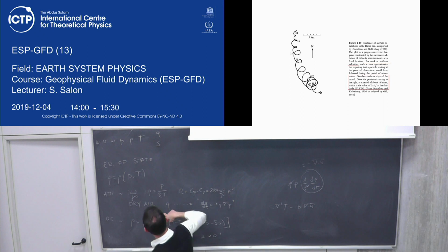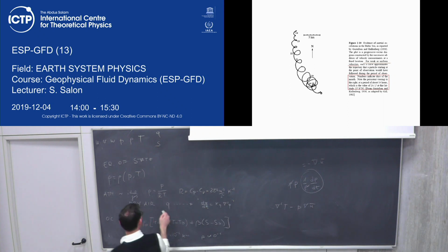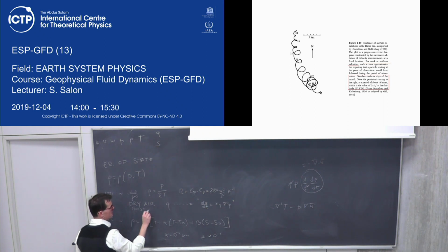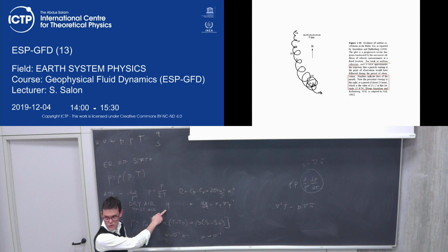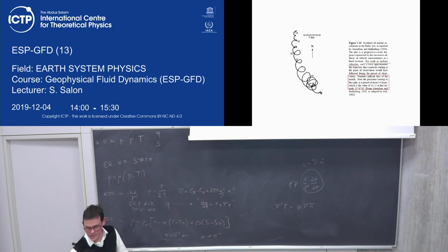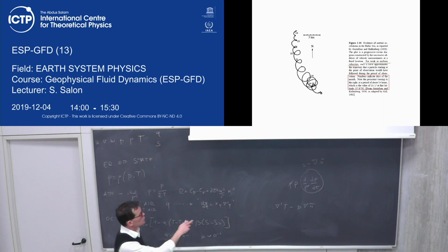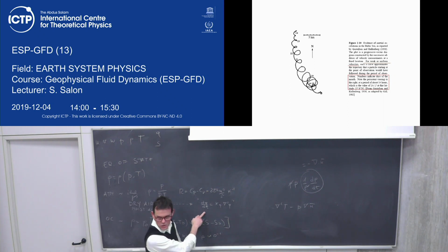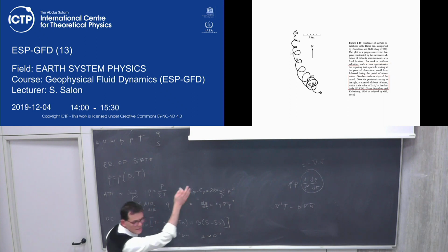So it is because for the dry air we are fine here. But since we have moist air, which is the most general case, we need to add also humidity. So humidity is one more unknown that we have to add to our system. For the moment, in order not to be crazy, we can say that the evolution of humidity in time is simply due to a diffusion. So just the Laplacian of humidity, with a certain constant of diffusion of humidity.